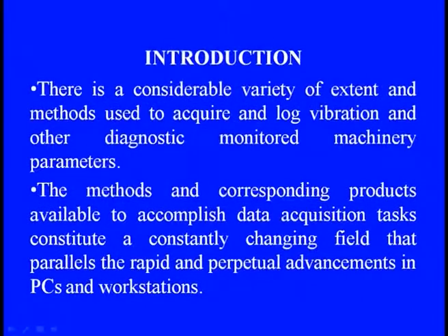There is a considerable variety in the extent and the method used to acquire and log vibration and other diagnostic monitoring machinery parameters, because the methods and the corresponding products available to accomplish the data acquisition tasks constitute a constantly changing field, with parallel advancement in PCs and workstations. When we are talking about online fault or online vibration signatures, we need to check how we can capture these data and process them.